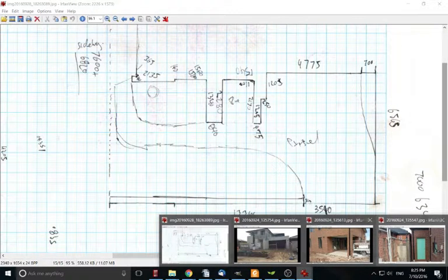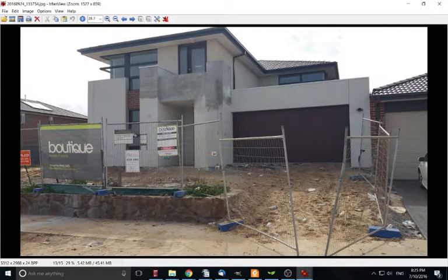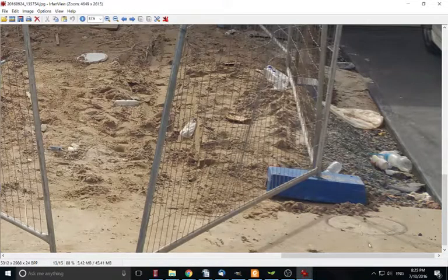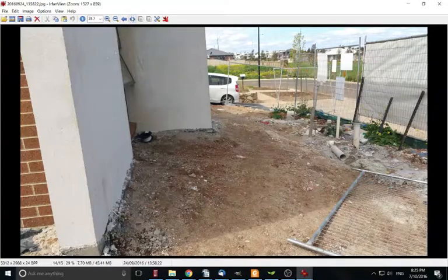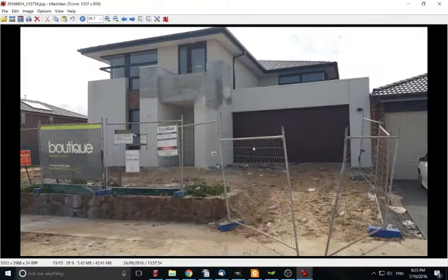If we look at the photo, you can see this pit here. There's a fault line in the concrete, and then the crossover. A fault line is usually an indicator of the boundary. There's usually a surveyor's peg there when they would have done the crossovers. The concrete has come in, and they would have put that right where that is, and that looks like it should line up directly with this gap here in the properties. That's what we're going to do, because we haven't really got much other choice at this stage.